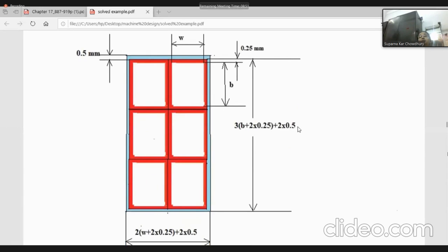Now, when we are going for multiple conductors, we can have circular conductor or rectangular conductor. With circular conductors arranged like this, there is contact only at one point, and so the total area divided by the conductor area is smaller. That is, much more space is wasted. That is one point. The second point is that any circular conductor has a minimum bending radius. So when we have to bend and make the winding, it is difficult with a circular conductor.